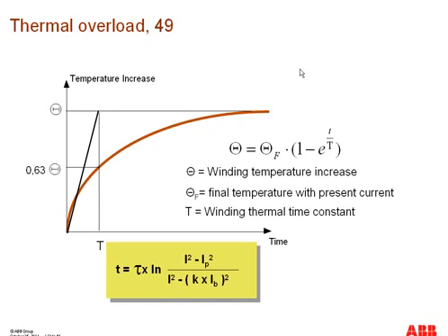Okay, so we were talking about this thermal overload protection. The thermal overload protection estimates the internal heat content of the transformer as well as the generator continuously, and then the estimate is made according to this thermal model right here. Normally, two levels are available. One level is the warning level, and the other level is the trip level.